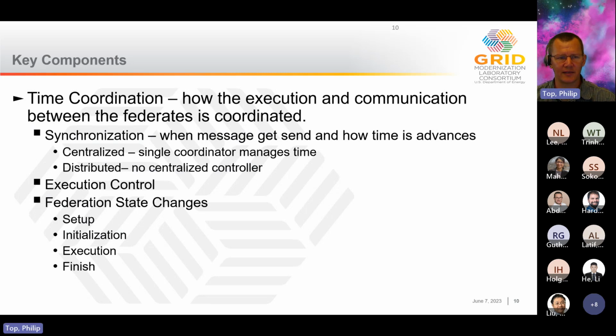Helix runs in a number of different states through the system. When you first create it, it is in the created mode or a setup mode. Then it can advance to an initialization mode. The transition from the created mode to the initialization mode is the only global time synchronized event in Helix by default. So every federate needs to specify that it's ready to go into the next mode. And when every federate is ready, then the central broker grants this request and then the simulation proceeds.